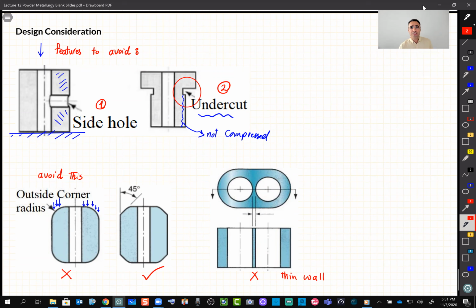So working with powder is not easy. So the process usually is automated. And you compress the part to the shape that you want. Usually we use this process for a smaller part, and for a part where we can make sure we can create a uniform layer by layer pressure. And we make a part, which we call a green part.